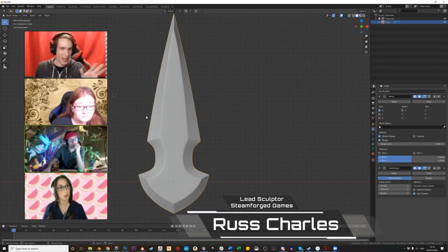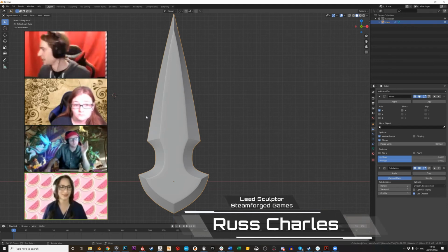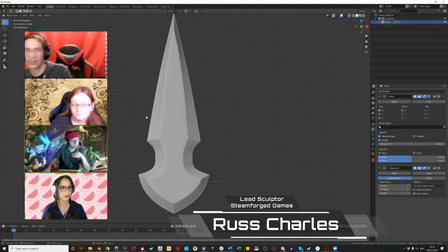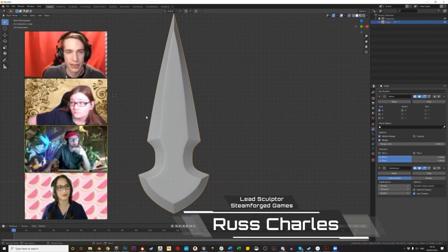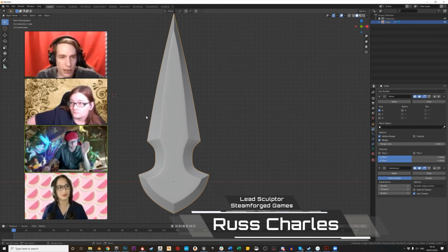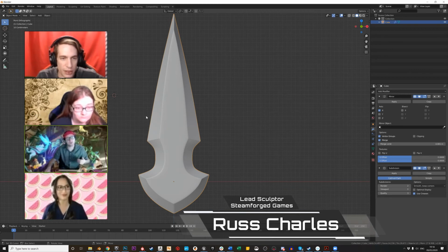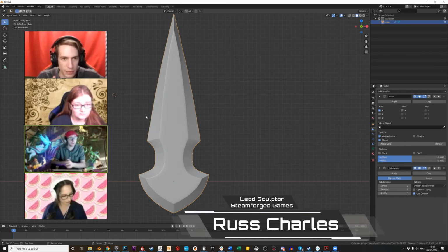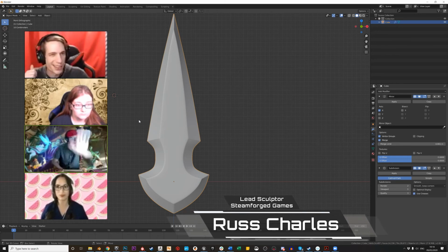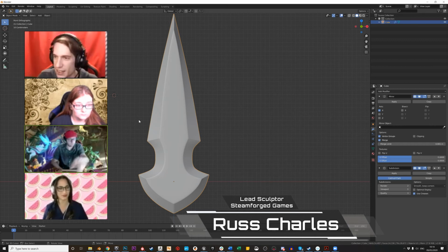My advice to you would be lay it on a plain coloured background, or hang it on a wall, whatever. Take a photo from at least 2 meters away with a decent high-res camera, and then crop that photo in and load it as a background image. You want to take it from at least 2 meters away to minimize the amount of perspective distortion that you get, and then you crop in to get the detail that you need. And then you can pretty much do a one-to-one trace in Blender. You could add that as a background image and do exactly what we've been doing, but you'd be able to follow all of the shapes, and it would show you exactly where to put all of your vertices.